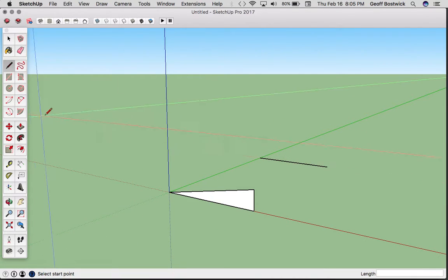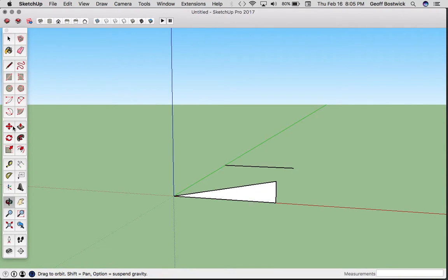with a line tool, and then you can take this rotate tool. Then you'll notice it wants to rotate it this way, but that's not what I want. I want to actually rotate this line this way. So what I did was I pressed my left arrow key. If you press right, it goes that way. If you press left, it goes that way. So I press left arrow key, click once and release on this point, click once here and release, and then you can specify. I can say I want this to be 12 degrees, or I can type in 15 degrees.